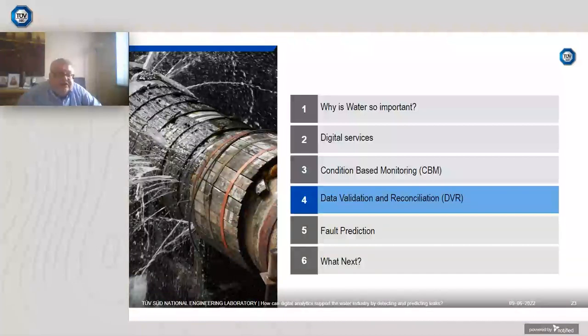Data validation and reconciliation can be applied to many different types of industrial plant, from simple systems consisting of only a few measurements to complicated systems with several hundred. Due to the large number of calculations involved, data reconciliation is particularly suited to software application. The basic function of the software is twofold. Firstly, to provide users with more reliable and accurate data, and to alert operators to instrumentation readings outside uncertainty bands.